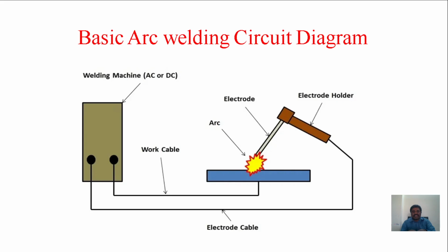I am giving the positive terminal to the workpiece and the negative terminal to the electrode, which is connected to the electrode holder. We call that straight polarity. Due to that, what happens here is a higher burn-off rate and less penetration will take place.